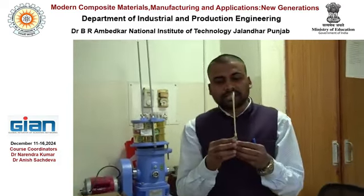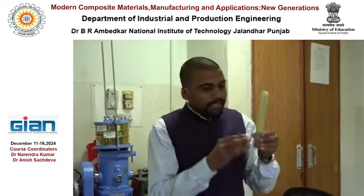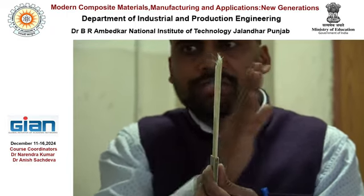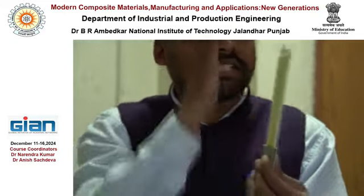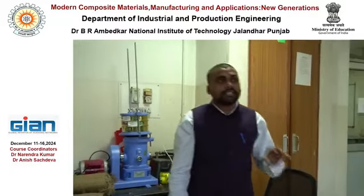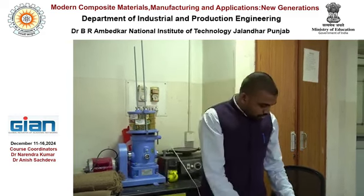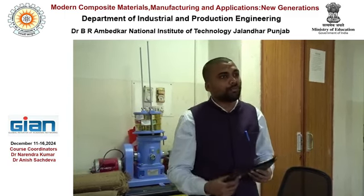If you look at the center, the moment of inertia effect will be there. You are applying load like this on this particular material, but the layers which are away from this center will take load differently, and the layers which are at the center will take load differently. That is one of the reasons why delamination occurs, because your individual layers are taking load differently. So how to then mitigate this particular problem of the composite material?